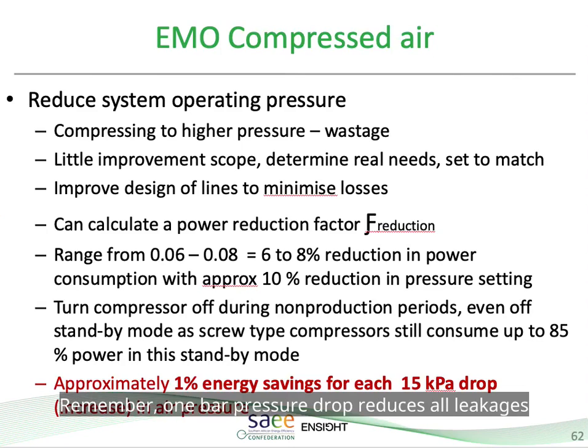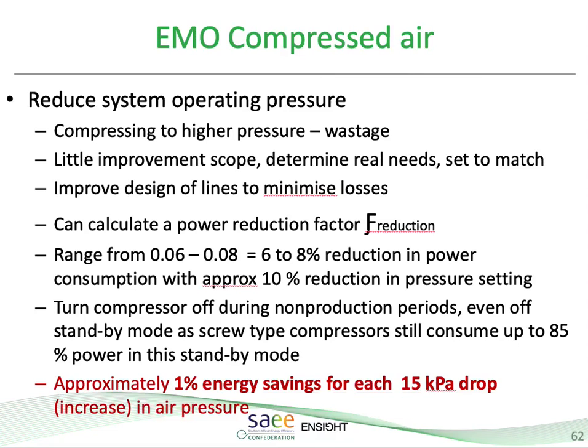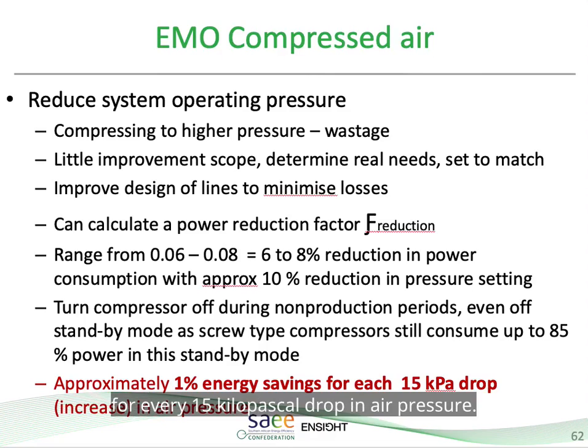Remember, a 1 bar pressure drop reduces all leakages in the system as well. Approximately 1% energy is saved for every 15 kilopascal drop in air pressure.